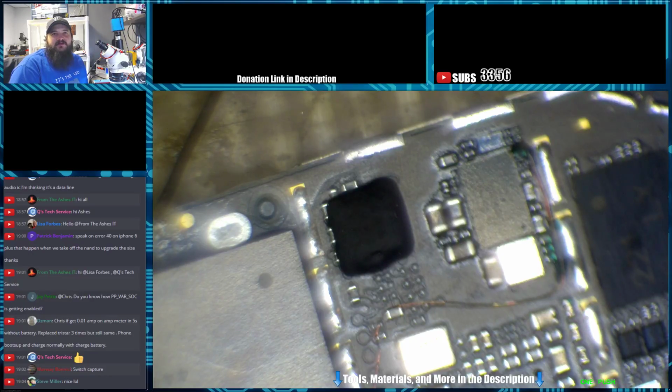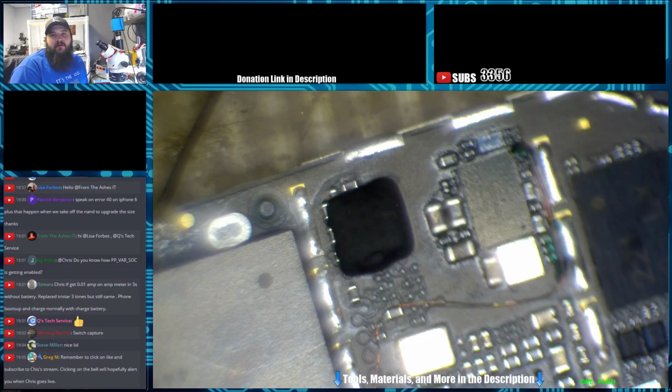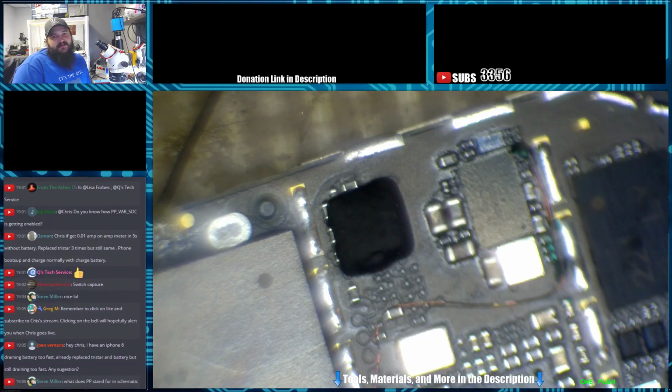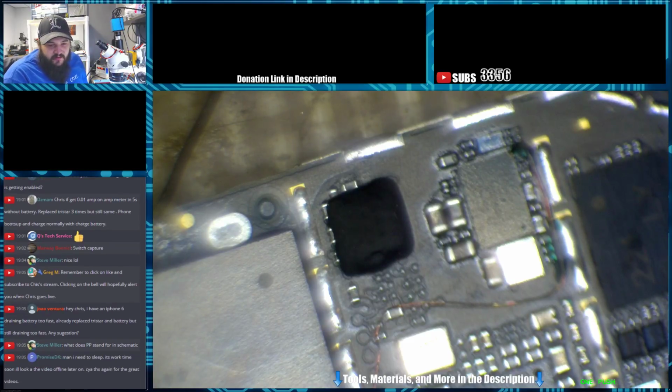Let's see, VAR SOC, and let's scroll up. Oh, no, maybe not. Hold on. Is there a filter here I'm missing? There's going to be a filter around. There it is. So, yeah, something with the PMIC is going to enable that. There's no other line for that. Now, you can hunt around the PMIC and see if there's maybe an enable line for those, but I would guess that that line is made only if certain conditions are met and the PMIC sees something. But I'm pretty sure that's going to be a PMIC problem.